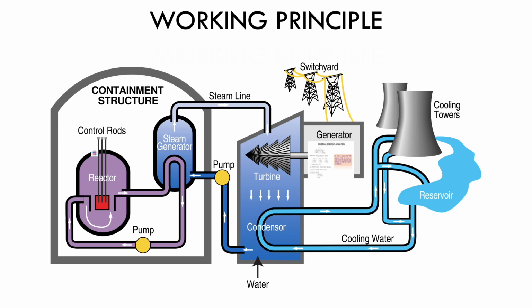In the pressurized reactor, uranium-235 isotope atom undergoes nuclear fission, and this reaction releases a lot of energy in the form of heat. The heat produced from this reaction heats the water inside of the reactor to approximately 327 degrees Celsius. The water here is kept at a high pressure of about 15 megapascals to avoid boiling.